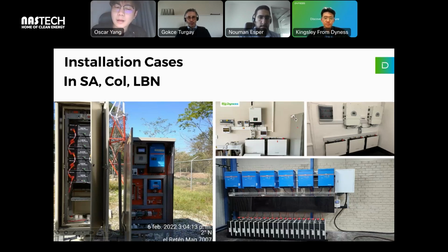If you are connecting battery packs in parallel, it is recommended that you install them in a rack, because it's better for cooling. But our battery has very good control and protection in temperature rising, and also for charge and discharge rate, depending on the real-time temperature. So if you put them together like this, it's okay, no problem.